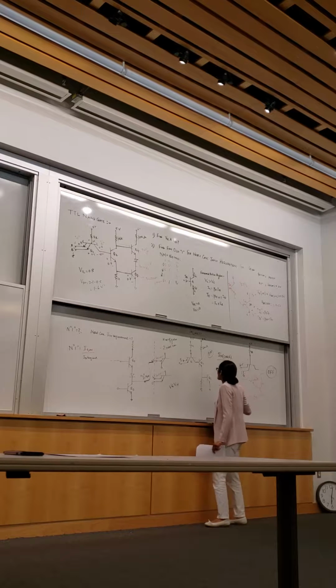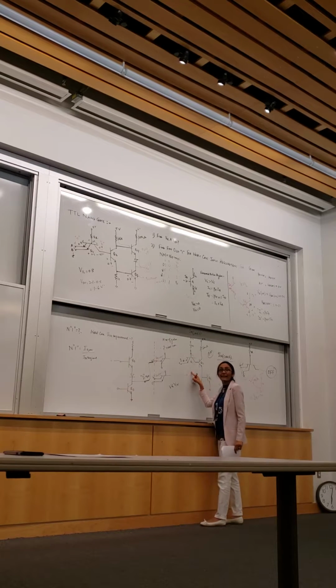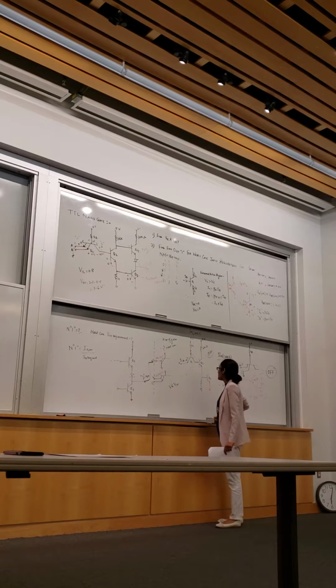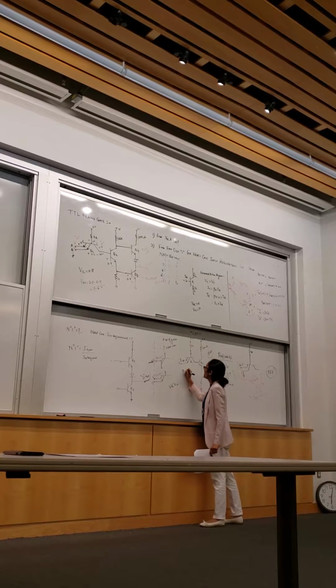If I had a transistor like this, which I drew in class, the base current would be split. But instead the emitters are embedded in just one transistor, so they have the same base current. So it's just beta R IB1. So here, your IIH in one input is beta R IB1.